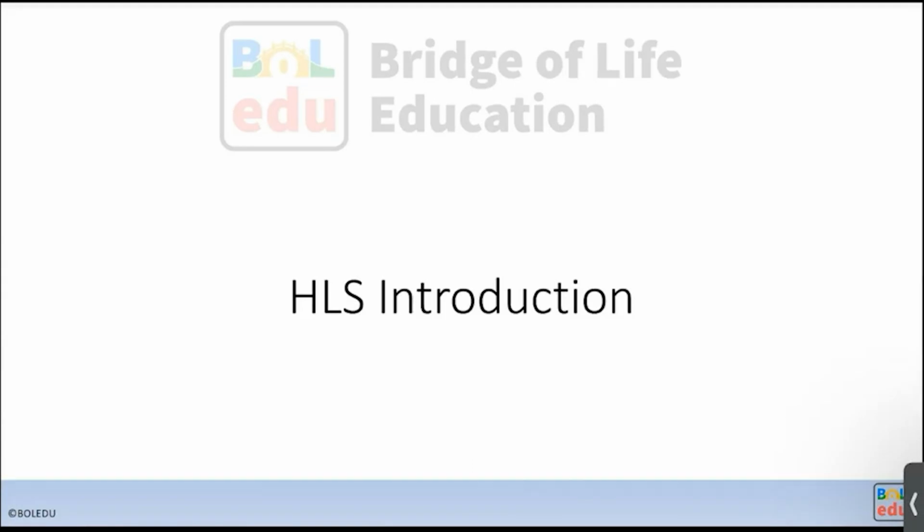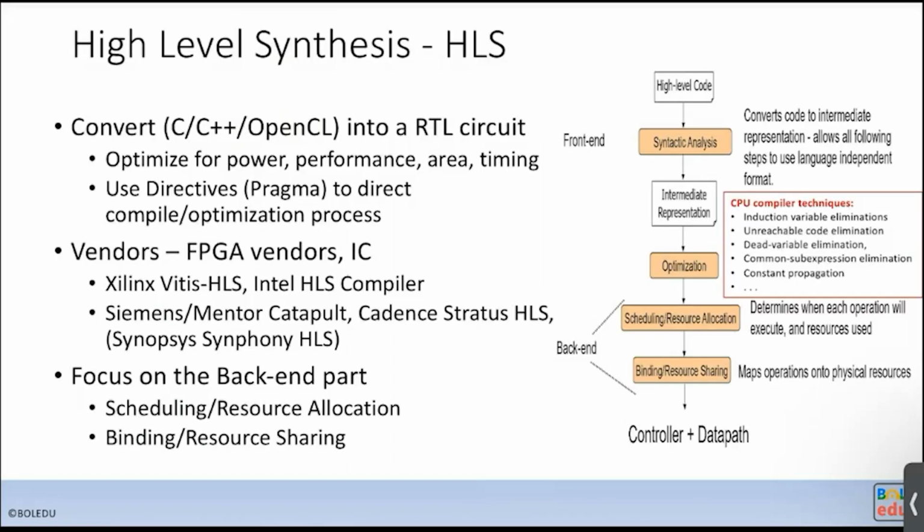Okay, the second part of the lecture is to give you a brief introduction to HLS. HLS means high-level synthesis. What it does is convert the high-level language, C or C++, into an RTL circuit. So basically it generates Verilog code or VHDL code. It does not generate the netlist.